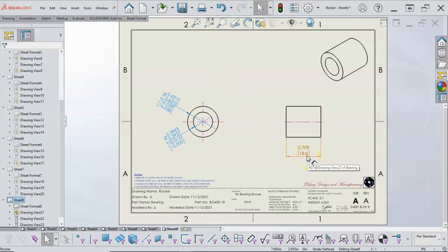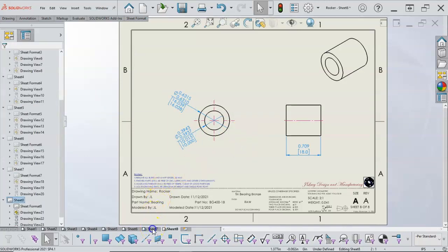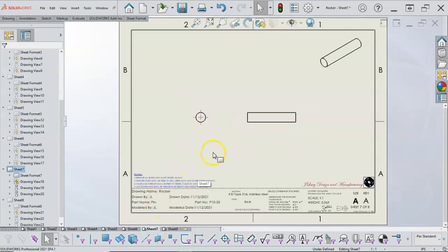So again, if we round, 1 millimeter is about 0.039, which means it's about 40 thousandths. If I divide by 10, 0.1 is 4 thousandths, 0.01 is 4/10 of a thousandth. So we're out pretty far to be dealing with three decimals on a metric number.